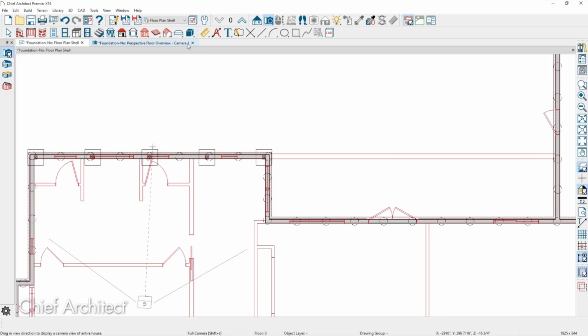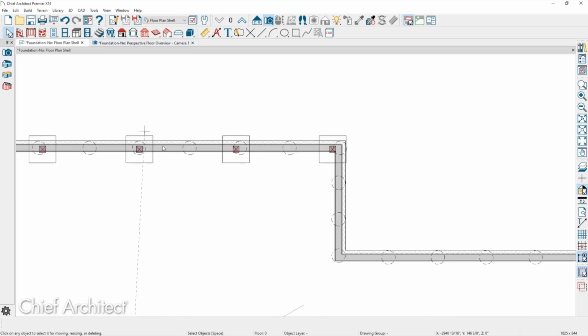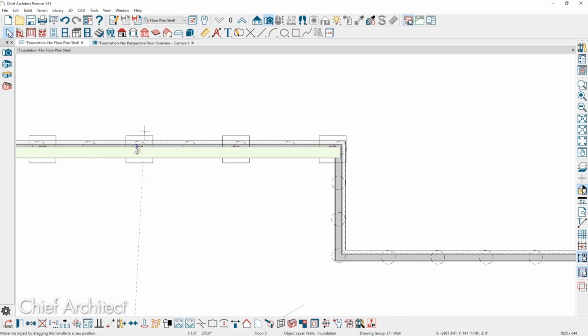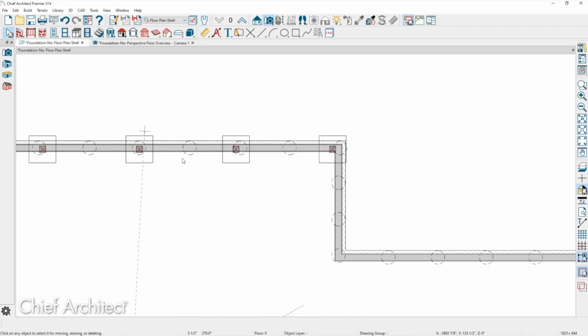I've tried using the piers, but what happens is that the beam falls in the center of each pier, which gives me a lift, and I want it to be flush with the wall. That is my problem using the piers. Posted footing feature. Because the piers give me an overlapping, there's no way to move it. Set the width of the piers equal to the wall thickness. Oh, yeah, but I need a 10-inch, it should be 10 inches. So that's my problem.